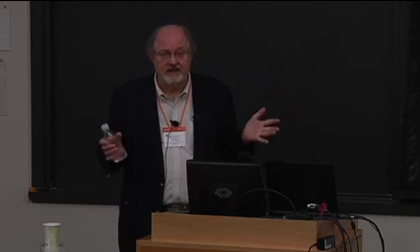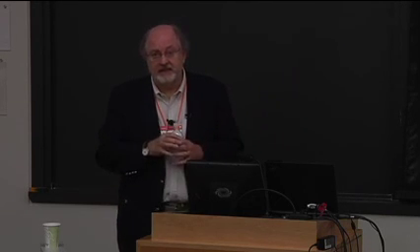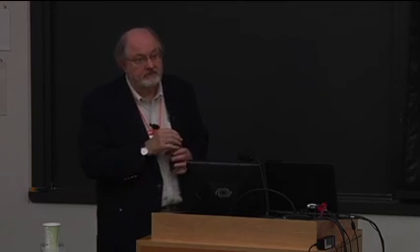Thank you for the lecture. On your reduction of a mechanism, my experience is that you can achieve a very compact mechanism when you only aim at predicting the auto-ignition delay. When you want to capture the laminar burning velocity, then it becomes very inefficient, and you have to add species there. So I'm wondering how much. Here, consideration is not really given to calculating laminar flame velocities. We're relying on somebody to give us those. You could get that from a detailed mechanism if you trusted it, or from experiments.